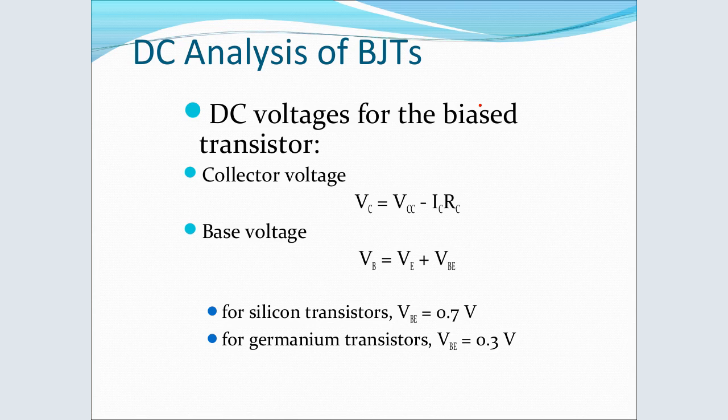So the resistor on terminal C multiplied by the amount of current flowing through that terminal. Then from there, you can get your voltage on the collector terminal. You can make any of the three the subject and compute appropriately. You can even decide to get VCC from those two other terms.